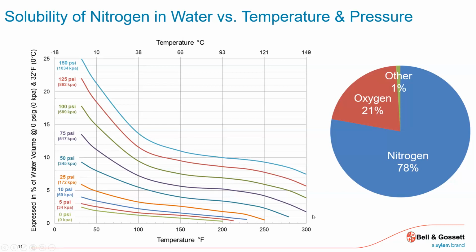But all it's trying to show here is based on either temperature or pressure. If I keep the temperature at a certain constant, as I change the pressure from 150 pounds and reading down, what they're trying to show on this chart is the percentage of air that is absorbed, that is soluble, in the water itself.